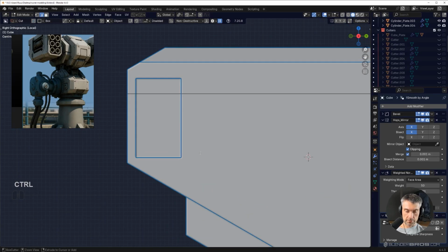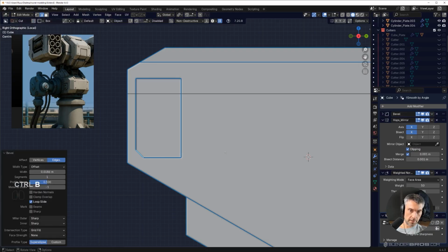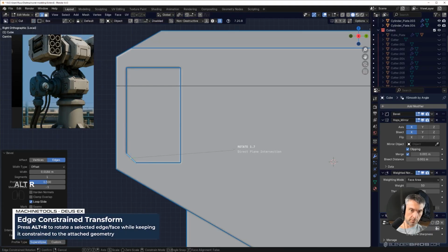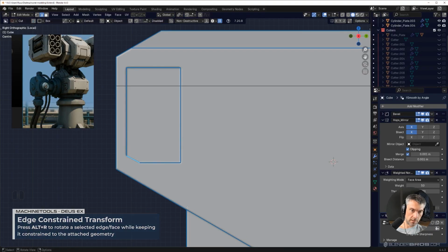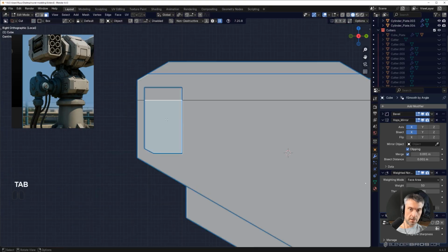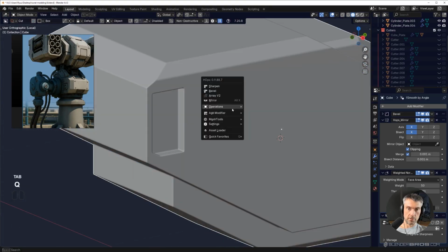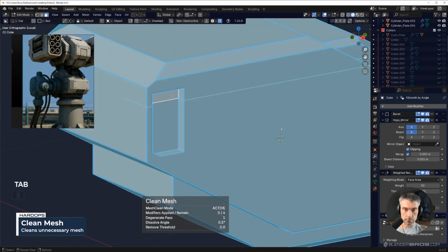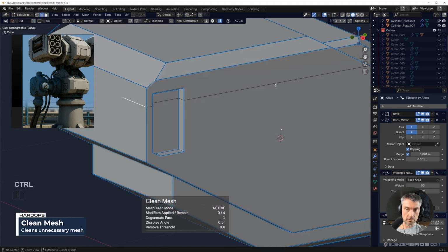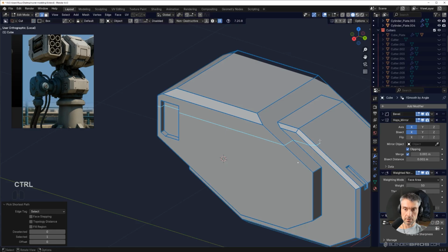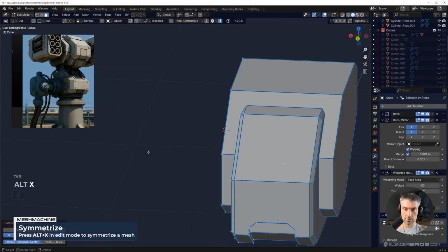And we could then use Shift curve extract to bring this plate up. So Control B here, and we could just align this with the bottom edge, right? So you can align with this one, echoes it, and then grab this and just clean this nonsense here. Why doesn't it want to clean it? What the hell is this thing here? Control X. What the hell is this?